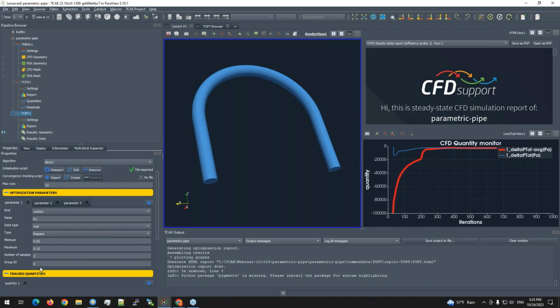for each parameter you define the minimum and maximum. You can choose if the dependency of each parameter is linear, logarithmic, or you can explicitly list the values you want to simulate, or values which can be given.